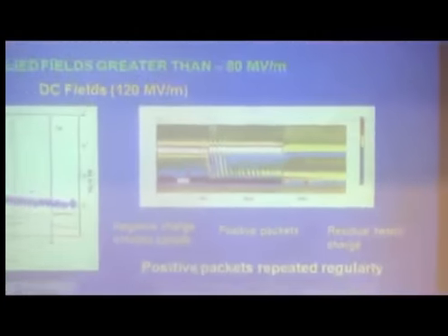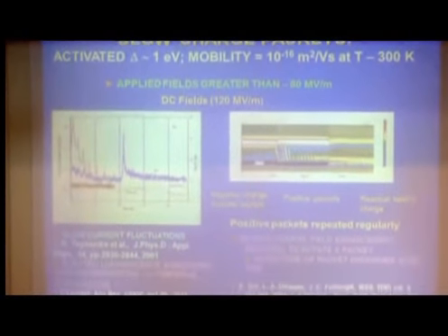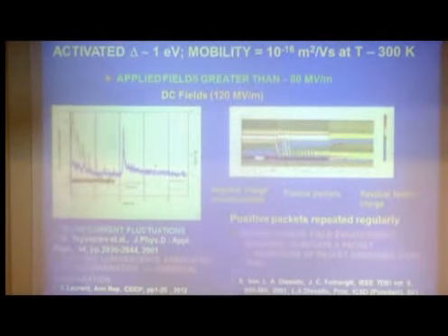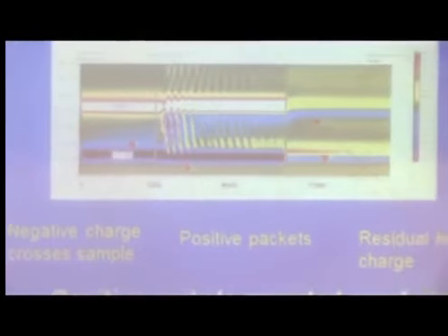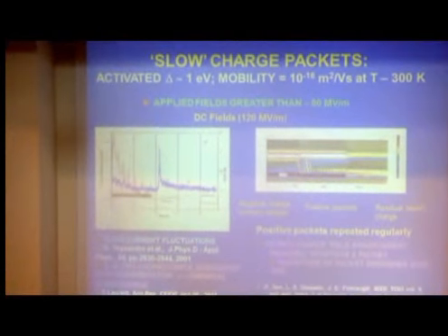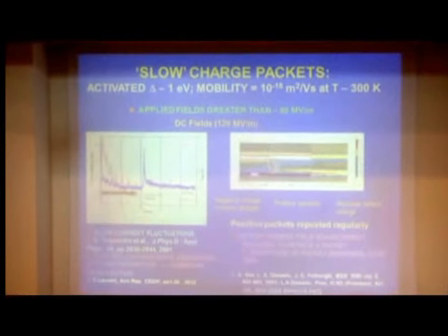They're sections that are peeled from a cable that, in this case, I think, hadn't been aged. What you see here is, at first, you just get negative charge coming across the sample. This is not a linear time base. That takes 48 hours. Most people don't have the patience to do PEA measurements for longer than an hour. But let me tell you, there are some very interesting things if you sit around for long enough.